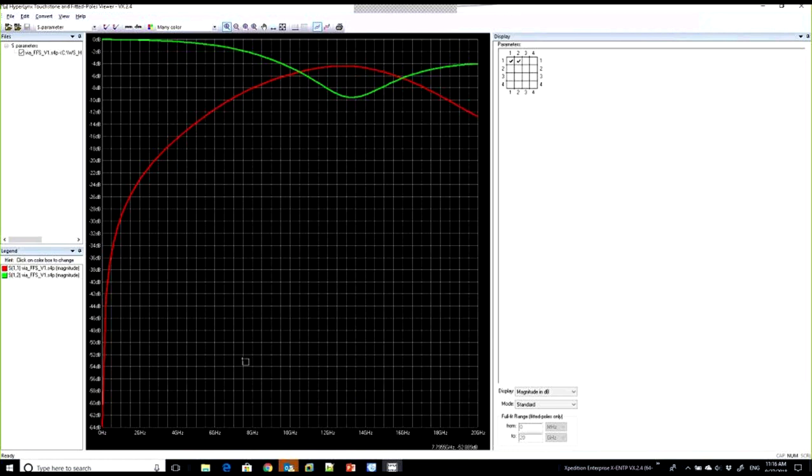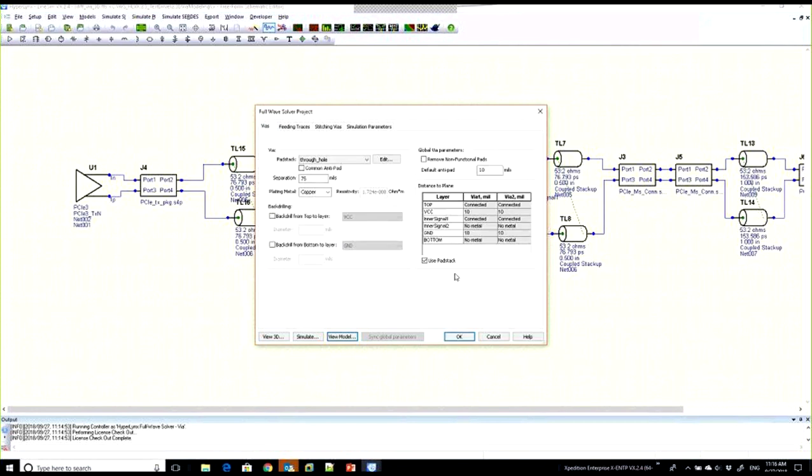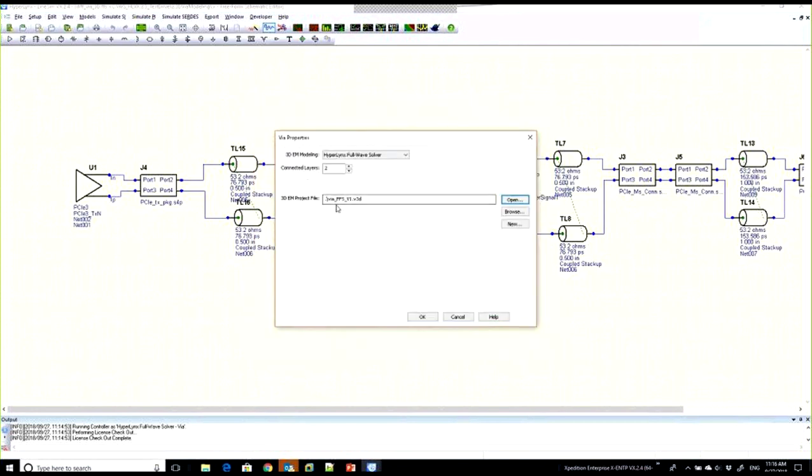So if again we're running below maybe 8 gigahertz or so, I think this looks pretty good for that. Up here, not so much. All right, so I think PCIe Gen 3 would probably be okay with this. Just guessing. All right, so that's the model we've got there. So let's just cancel that. We've got this. So we're pointing to that model for that structure.